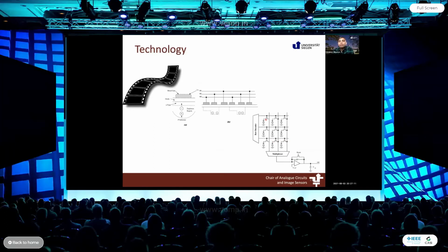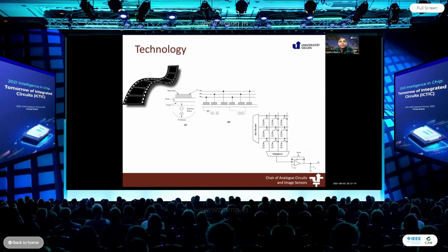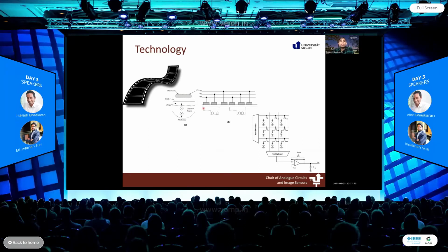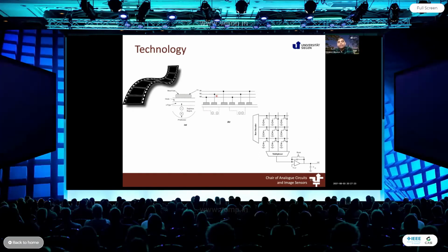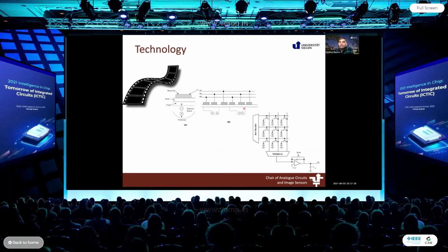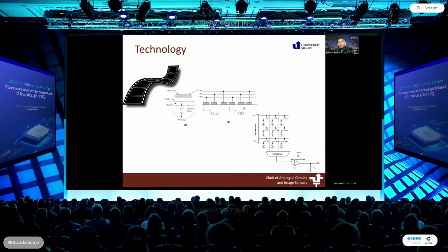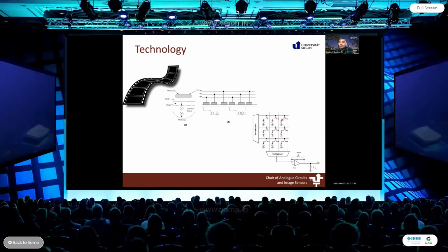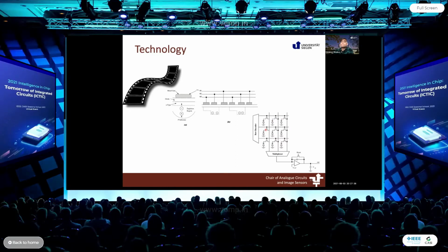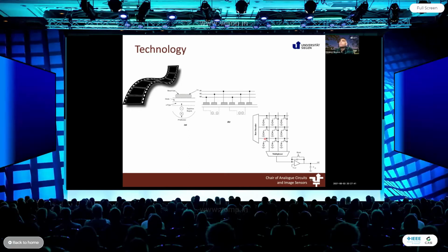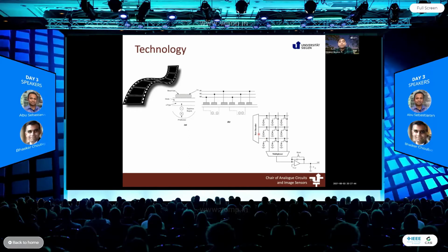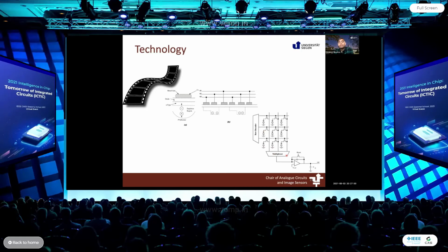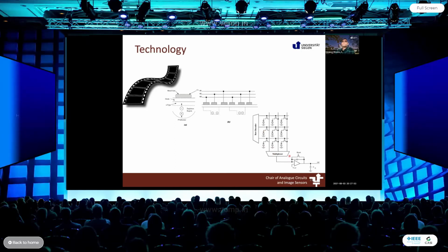And those who are a bit older might remember the charge-coupled devices, wherein we created just a bank of capacitors where light falls on it, generates charge pairs, and then we transfer these charge pairs all the way towards the end and read them out as an image. Earlier in the days of silicon, we also had simple things. We could just have arrays of photodiodes. So there's a 2-dimensional array of photodiodes with a switch connected to each one of them, very much like your crossbar architecture of one resistance, one switch. You have row decoders, column multiplexers, light falls on the diode, generates a photocurrent, you read out that photocurrent, and you have got an imager.